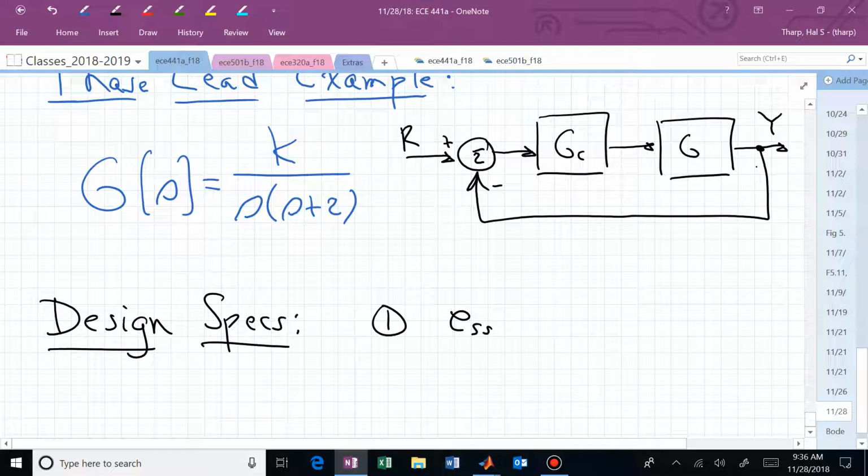You're stuck at -1, aren't you? So you're not changing the settling time by increasing the gain K. What will you do if you just continue to increase the gain K? What kind of step response behavior will you obtain if you keep cranking up K? Your percent overshoot is going to start getting bigger and bigger, isn't it? And you may not like that.